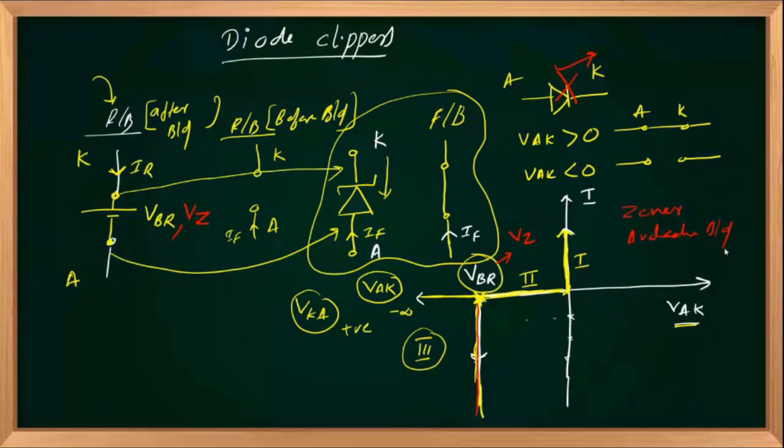So the avalanche breakdown mechanism involves collision between atoms and complete damage of the atomic structure, whereas Zener breakdown happens at lower reverse voltages. This mechanism is visible even in the low reverse bias ranges, whereas your avalanche breakdown mechanism occurs for higher reverse voltages, right?